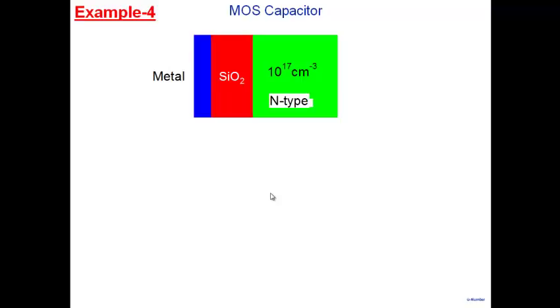I think all of you can sketch if I give you the value. What do you need for metal? What information do you need about the metal to sketch its energy diagram? Work function, right? SiO2, think of it like a wide band gap semiconductor. So what you need is again electron affinity and energy gap. And this is silicon, electron affinity, energy gap.